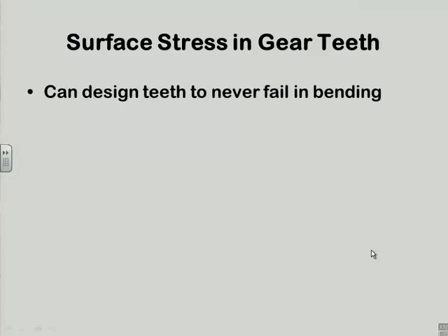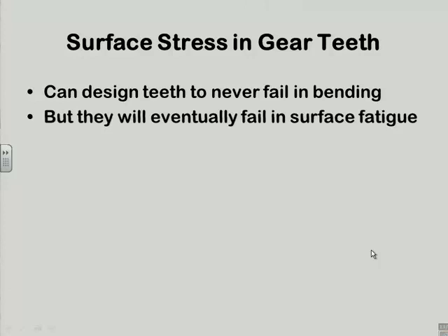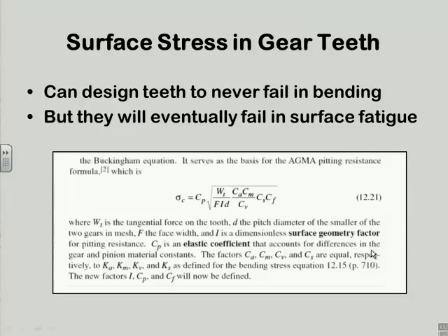Okay? Are there any questions at this point about bending stresses? So this is the one that they will succumb to eventually. So as I said earlier, we can design them not to fail in bending because we have infinite life possible, but they'll eventually succumb to surface fatigue.